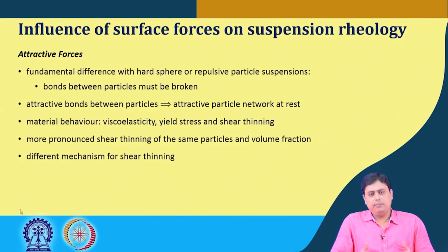This kind of behavior is typically seen in suspensions with attractive particles. In this case we have more pronounced shear thickening for the same particles and same volume fraction than in the other two cases, the hard sphere behavior or the repulsive force behavior, and the shear thinning mechanism is also different from the non-interacting hard sphere particles.